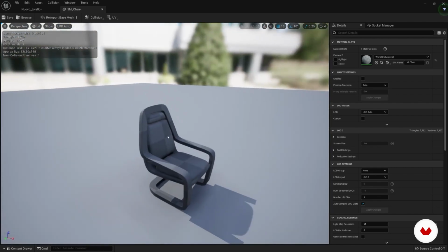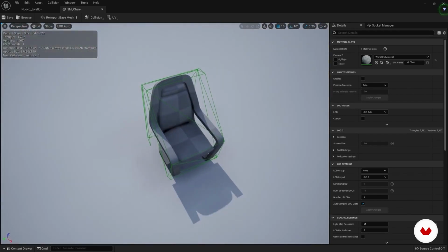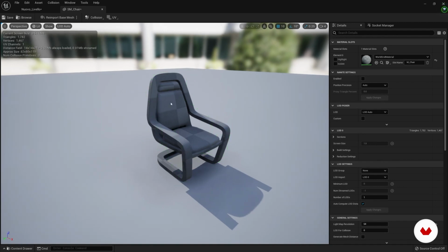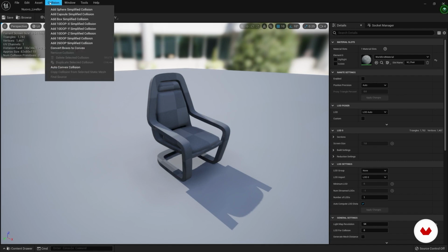An important thing that we can see in the static mesh management window are collisions. If we go to show simple collision, we see what the collision of this object actually is. Because not always the general mesh, the polygons that make up an object, is actually its collision. Unreal generates this outer mesh with a lower number of polygons, and this is where the objects will collide. You can edit, delete and create one from this window.